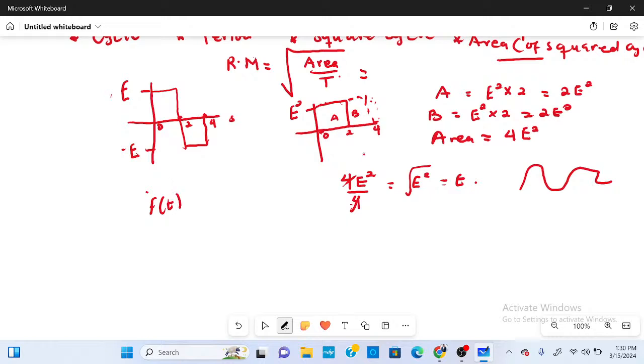Whenever you want to find the area, or sum the area, we use an integral. So the integral is from 0 to our period, because we are summing from the time it started to the time it ends, and that is the period, from 0 to T, with respect to t, right? Then you divide this whole expression by your period. This gives us the average. So mathematically, this is the formula we use to find the average for any waveform.